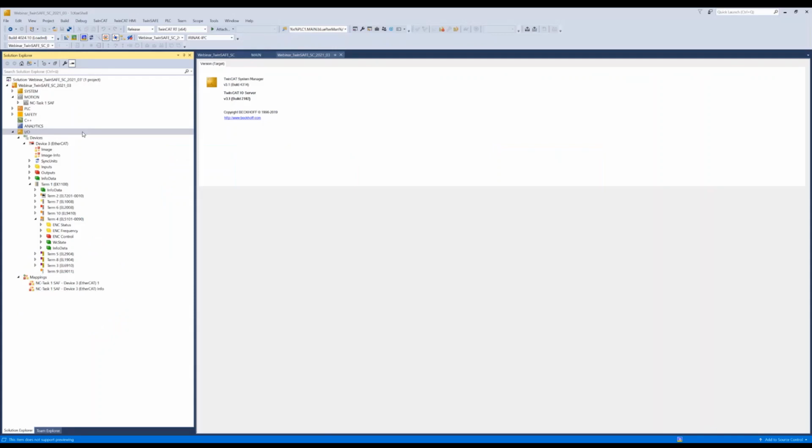Let us check now the configuration on the TwinCAT side. Here once more the setup. So we have the standard components, we have the TwinSAFE single channel terminal, and we have some safety components like the logic module and safe inputs and outputs. In the first step, I want to show how the parameterization of the TwinSAFE single channel is working. In the default settings, the TwinSAFE single channel terminals look like the standard terminals. To enable the TwinSAFE single channel technology, we need to activate this communication.